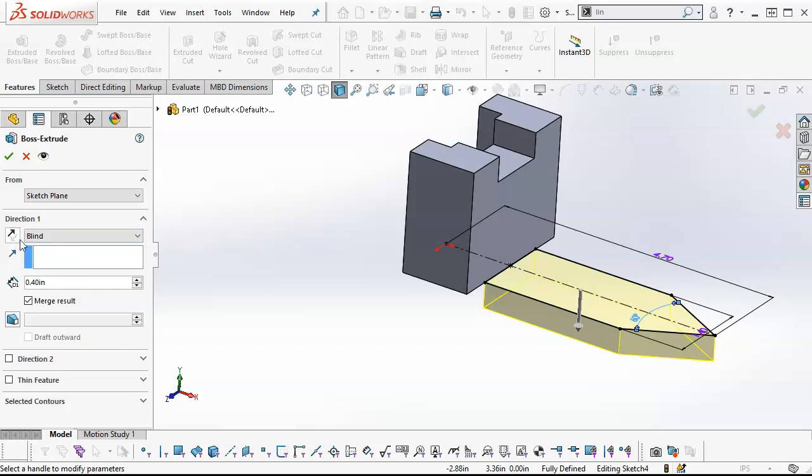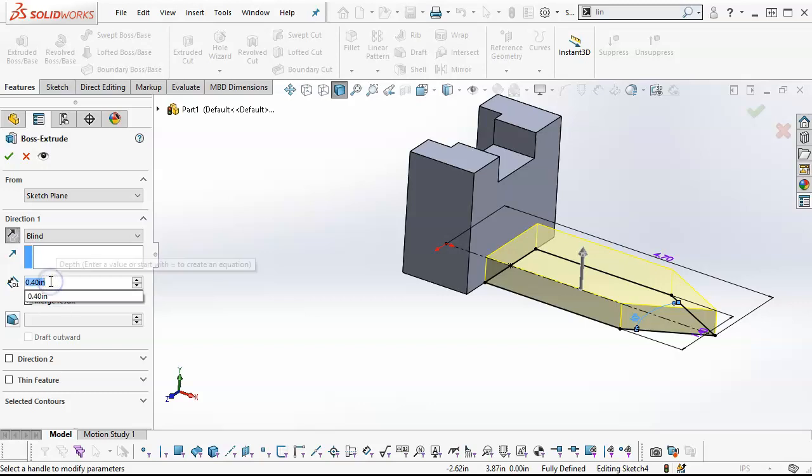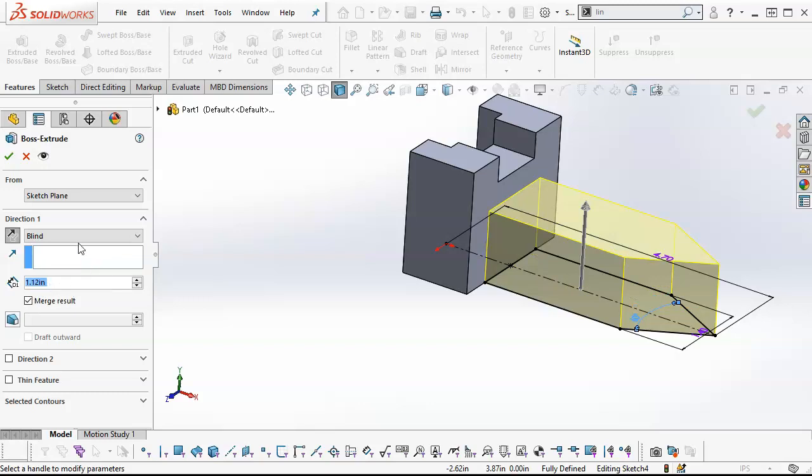So anytime you see the little box around one of the items, you're going to be able to reverse the direction. You're going to be able to make that selection. So in this case, apply draft. If it doesn't have the box, then you're just entering information for that group. I can also come out and grab onto the arrow and drag it the other way. All right, so it gives me my dimension. We're going to go in with 1 inch 120, and that gives me the depth.